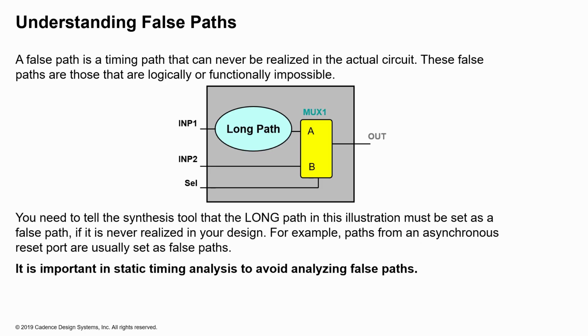It is important to eliminate false paths so that the tool does not spend cycles trying to analyze these paths. Some Cadence software automatically flags these paths as false, removing the need for in-depth analysis of such paths by the logic designer. But you need to run those tools in order to identify those paths before you run static timing analysis on your design.